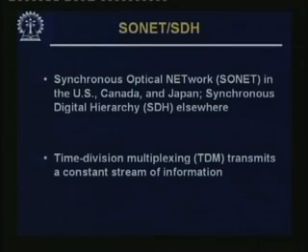Good day. So, in this lecture we will discuss SONET. The word SONET stands for Synchronous Optical Network, SONET, in the USA, Canada and Japan, or Synchronous Digital Hierarchy elsewhere. For example, in India we usually call it SDH. So, this is a time division multiplexing system that transmits a constant stream of information.